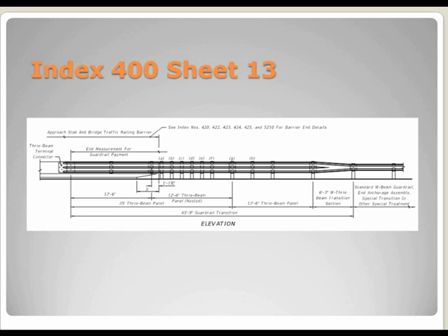So all of that guardrail is calculated as W-beam. There's no differentiation between the Thri-beam and the nested beam and the 6'3" W to Thri-beam connection. We've gotten a lot of calls on that, and it's been confusing for some of the newer designers, so the older designers pretty much know this has been standard practice for quite a while.